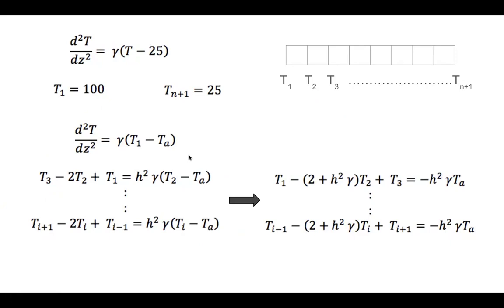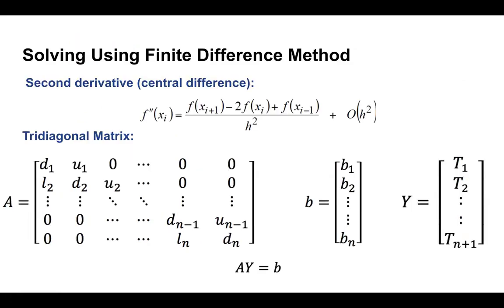It's better that you take a pen and paper and try to do it manually so that you understand how this grid is formed. So once you have that with finite differencing, what you have to do is just invert this matrix and multiply it with the constant matrix, and then you will get the temperature values. I hope you understood this finite differencing. If you have any doubt, please do ask me right now.